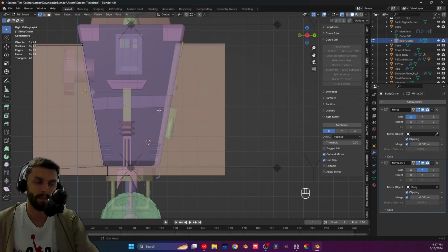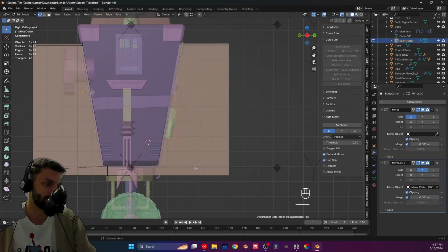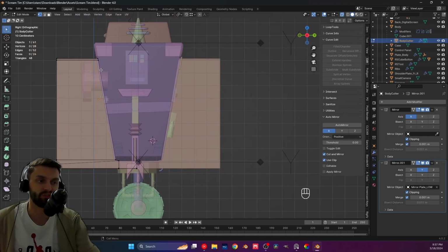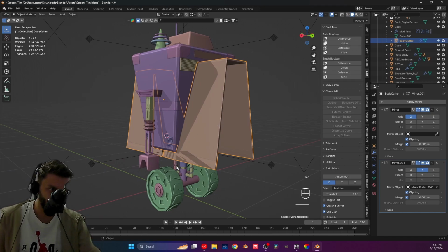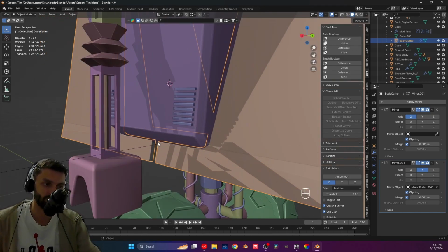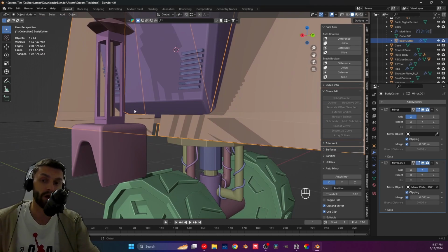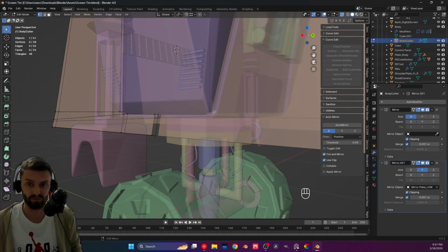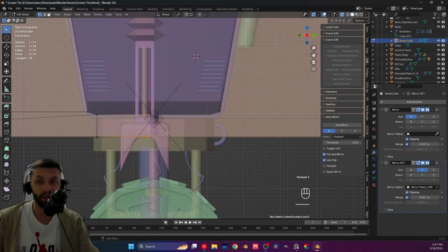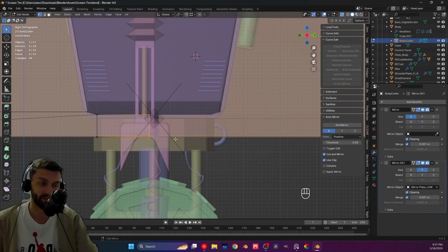It's not going to be perfect for what I have, because I have a trapezoidal body. So what I'll do is, instead of the body, use the empty I created at the base of my body for the mirror, which is going to make a perfect mirror for what I need. And now we have, as you can see, and again, this is exactly the perfect way for me to explain to you why you want to do it with a non-destructive method, because if you see errors like this, you can fix them. However, if I use the bool tool, well, good luck with that. We would have a way harder time fixing this.